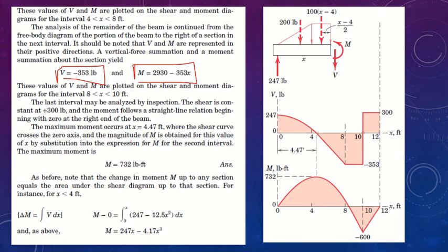Now we are going to use our equations and we are going to distribute our forces. We're going to write the equation of the general moment diagram, moment forces and shear forces, and we are going to develop a curve from 0 to 4. If you remember, the first set of equations is going to work from 0 to 4, up to the point here.